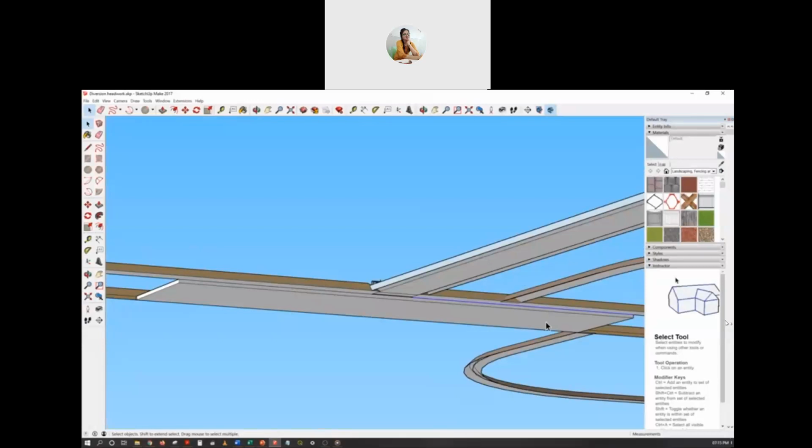This is provided so that water doesn't enter the river bed very close to the weir and get released just at the downstream, because in that case it will be a very small seepage length and lots of seepage will occur. So it will not be able to store the water.